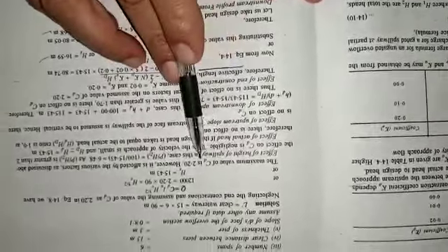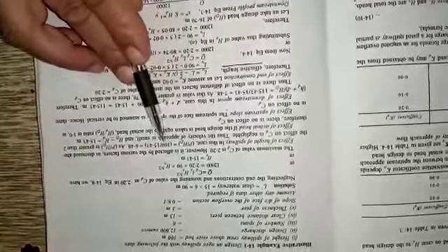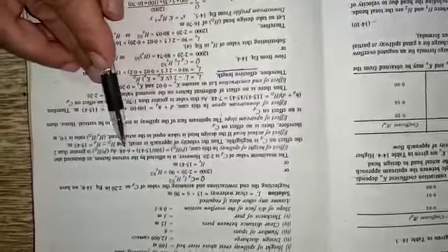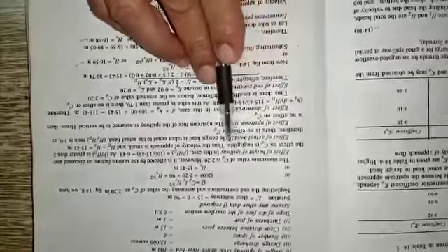Now, here the maximum value of CD is 2.2. However, it is affected by various factors like the height of the spillway, P by HD. In this case, P, the height of the spillway, is given as 100 meters. HD, as we have calculated, is 15.43. So P by HD comes out to be 6.48. As P by HD is greater than 2, the effect on CD is negligible.